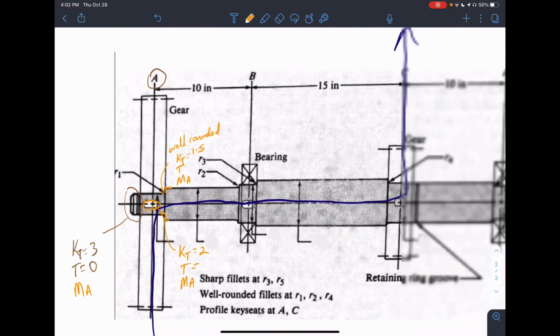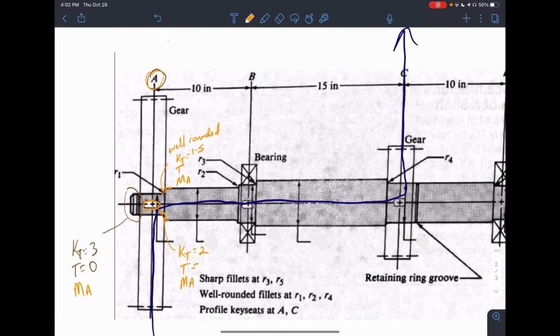So we could see at A there will be 3 diameters, D1, D2, and D3. So there will be 3 minimum diameters. And what we will do is choose, of course, the larger of those 3 minimum diameters when we calculate them. Now, this is being done in Excel, so it's a matter of dragging equations. We enter the equations once and we drag it down, and we will see D1, D2, D3, and we take the larger one.